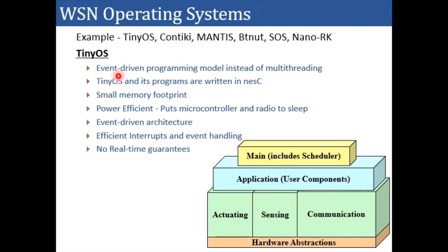TinyOS is an event-driven programming model, which is different from our conventional multi-threaded programming. TinyOS and its programs are written in nesC, which is a very lightweight version of C. It has a small memory footprint. It is power efficient. That's why it puts microcontroller and radio to sleep as much as possible. Event-driven architecture. It has efficient interrupts and event handling capability. But in TinyOS, the real-time operation is not guaranteed.